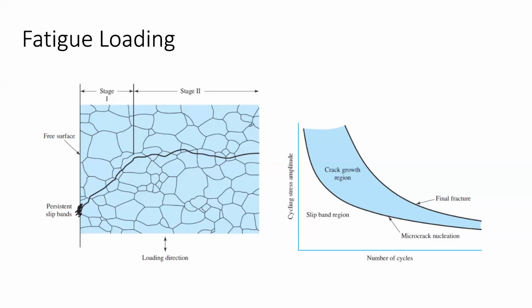Fatigue in general occurs because not all materials are homogeneous. You have something that you might recognize called a grain structure within metals. As I alluded to before, metals typically, when you make them, are not homogeneous. They have these regions of different chemical composition or just physically different bound atoms, which are called grains. In general, the reason fatigue originates is because you have what are called slip regions between these grains. And those slip regions are areas for stress to concentrate.